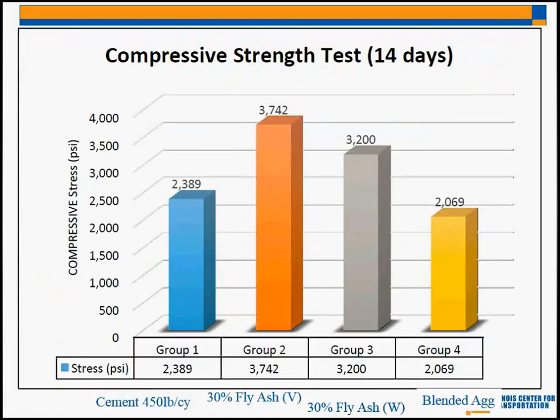This was work done in the last semester, and it showed great variability in terms of compressive strength of RCC with that recycled concrete aggregate, which mainly shows the variability in the absorption capacity of that aggregate and how it may not be the best material for RCC, at least in terms of this study.